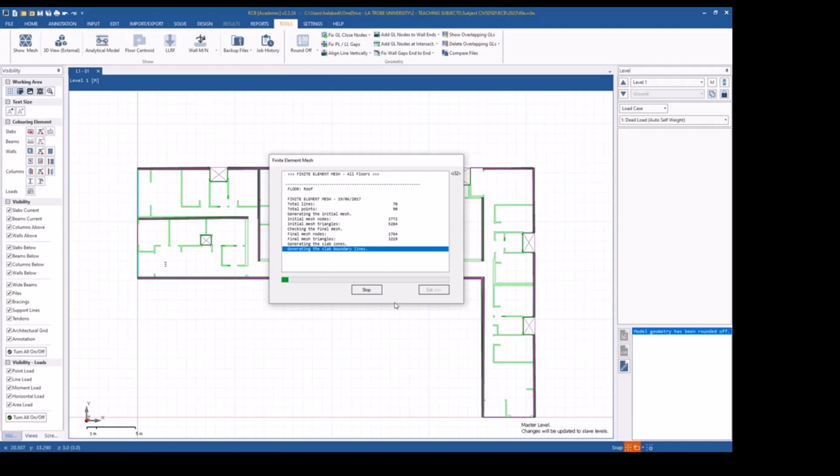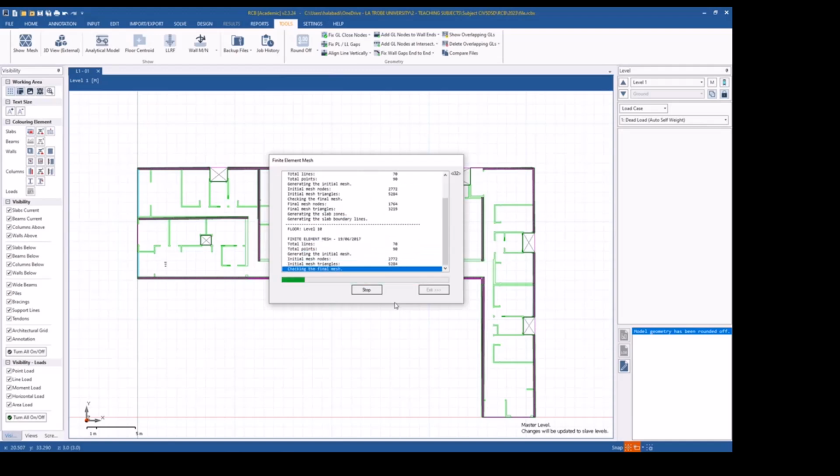Maybe I said ignore what you changed, but I'm just doing it again. So what I was talking about is the meshing. Basically, you're dividing your piece of slab into smaller elements that will use the elastic theory and go through all the matrices that we have to define all the stress distributions for the slab. So again, I can see that it's smoothly cruising.